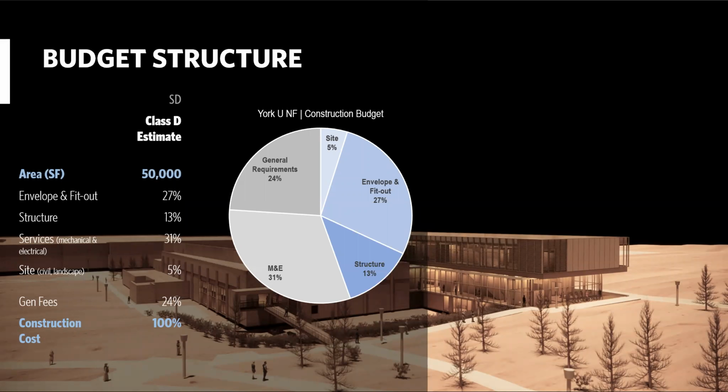You can imagine it was very frustrating to find ways to cut 15% out of less than half of the construction budget. For example, even if we had decided not to do mass timber, we would have had to replace it with another system like steel structure and add other finishes such as ceilings for fireproofing. Well, we actually costed this option and it turned out to be a wash, if not more expensive. So basically, no value engineering could get us the savings we needed.